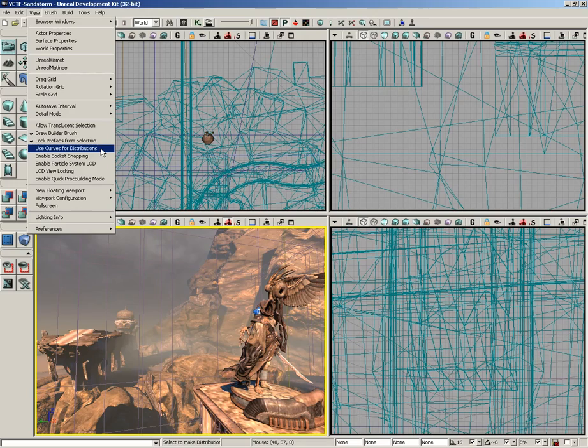And so to save on the processing power of having to do that, UDK will bake everything out into what is called lookup tables. It's just kind of an internal chart where it says, all right, at 1 second into your life, you need to be this big. At 2 seconds, you need to be this big, and so on and so forth. However, this simplification could potentially lead to problems if you're not getting the results you want. Perhaps you need it to be smoother to really see what's going on. And if that's the case, you can switch on Use Curves for Distributions to help you debug such problems.